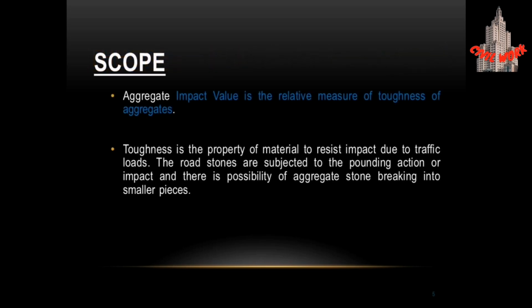Coming towards the scope of the impact test, the aggregate impact value is a relative measure of the toughness of aggregate. The impact test is a type of quality control test for highway pavements that is used to determine the suitability of aggregates for use in highway pavement construction.